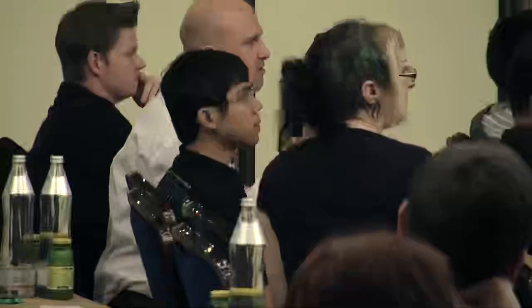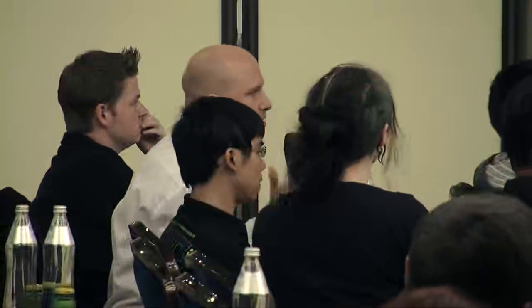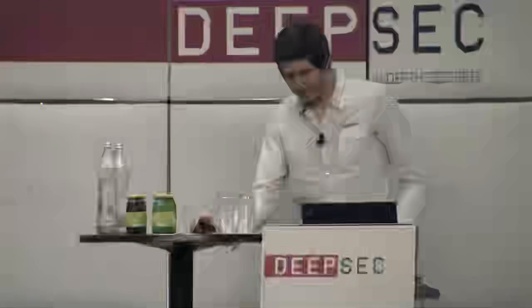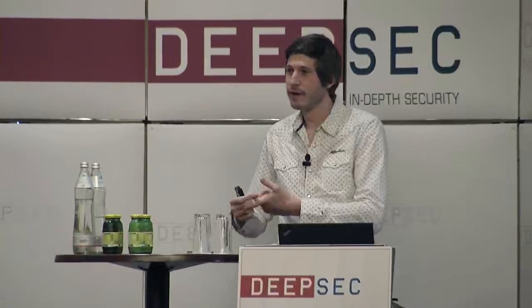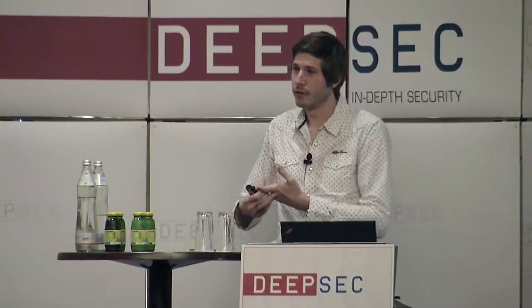You had the statistics about the timings for the response of keystrokes. How stable are they across different keyboards in laptops? Let's say this is a Dell, this is HP. How stable are these numbers? Yeah, that's a good question. The problem is, like I said, I implemented it for my computer and it worked for my system. It basically depends if you count the number of clock cycles on the CPU too, on the keyboard controller you have on your main board, and on the microcontroller within the keyboard.